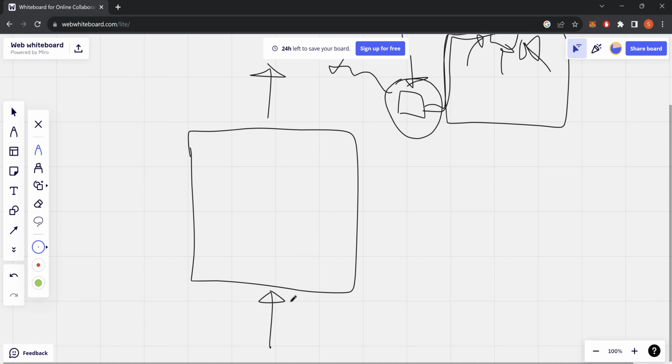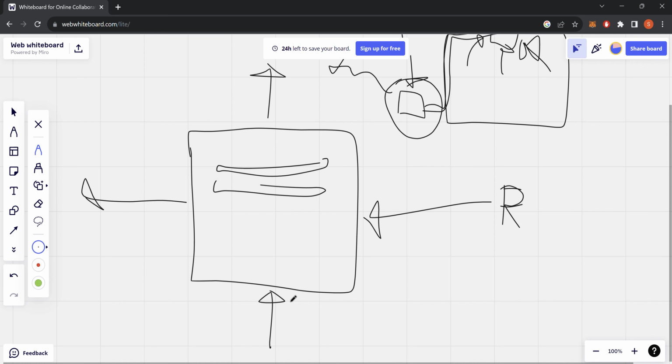The other fluid is the Freon or the R134A, and we're going to draw that moving sideways through this thing, even though it's not necessarily that simple. So basically what happens is the Freon, or I keep calling it that, but you call it whatever, refrigerant, I should just call it refrigerant, is going to contain that energy from the house, and it's going to flow through a bunch of little pipes. And those little pipes are going to have lots of aluminum fins on them. And those aluminum fins are going to be parallel with the direction of the airflow. So there's going to be a big fan that's going to blow all the air past those aluminum fins.